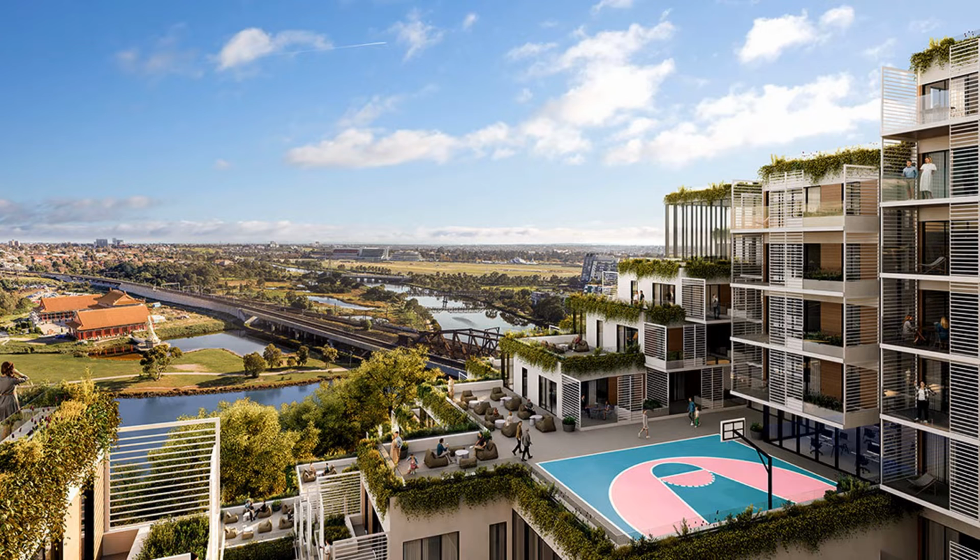So, another elevated view showing the public recreation. There's an actual basketball court on the roof, showing how occupiable the roof is, and by stepping the building, you're getting light deep down into the courtyard and into the lower units, rather than just having an extrusion go vertically straight up. This is also a structural thing. By stepping back, you're reducing the vertical cantilever of the project. Instead of being a flagpole in the ground, you're stepping back and creating a little bit more stability.